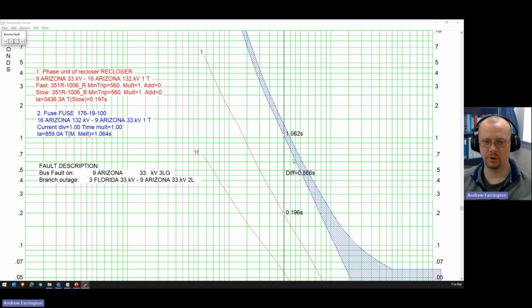You'd want to be more thorough in your approach for which outages to run than we just were. I just kind of picked some, but that's generally what you do. And I like to run all the faults, even if I think I know what the worst case is going to be, because sometimes you're surprised. And especially early on in my career, doing it this way, I learned things, because things would happen that I wouldn't expect.